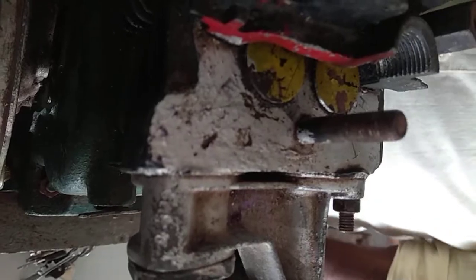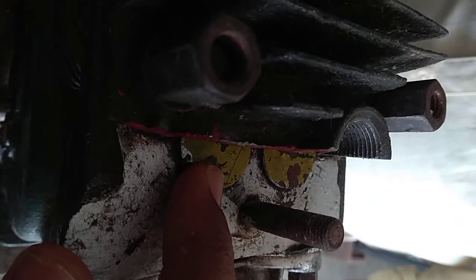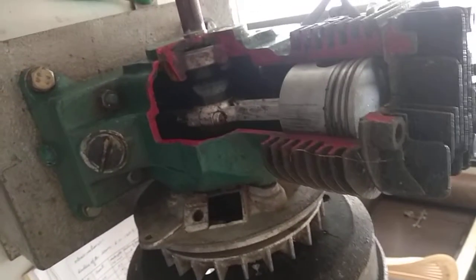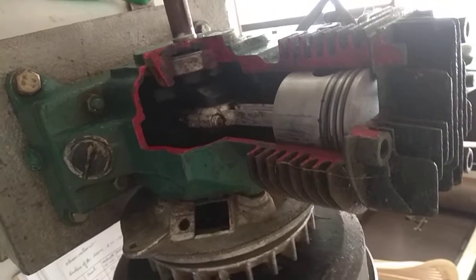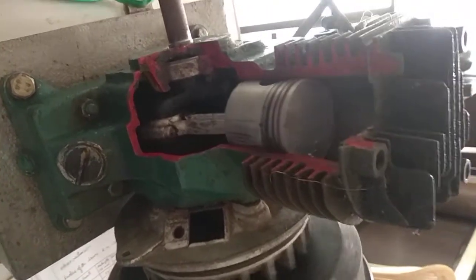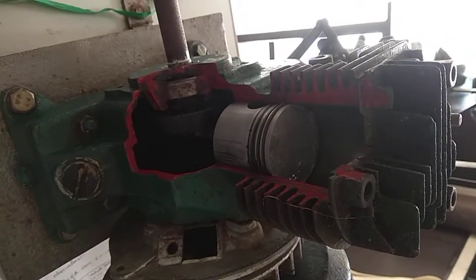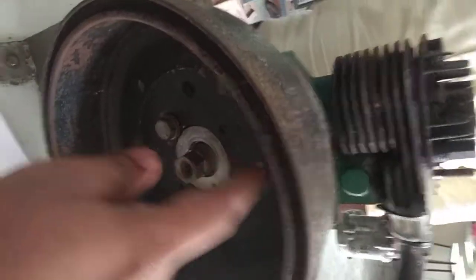These are the valves. This is an inlet valve and this is an outlet valve. When you rotate this wheel, the piston moves. So note down the TDC, that is the topmost position, and BDC of the piston, and then measure the radius of this wheel.